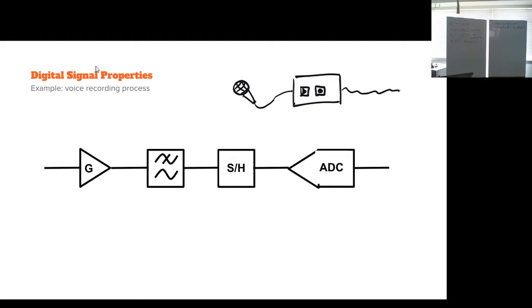Usually, when you're looking at an A to D converter chip, it usually has at least these parts on it already. If it's an A to D converter designed for voice, then it has all of these parts. And usually nowadays, that's adjustable by some software interface. Same for that one. The sample and hold automatically works with this A to D conversion, and of course, somewhere there's a sample clock.